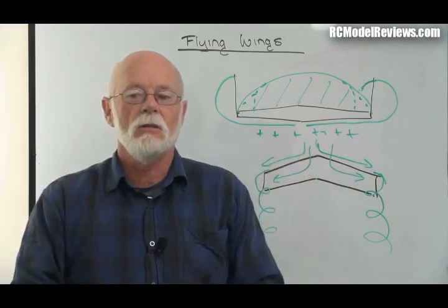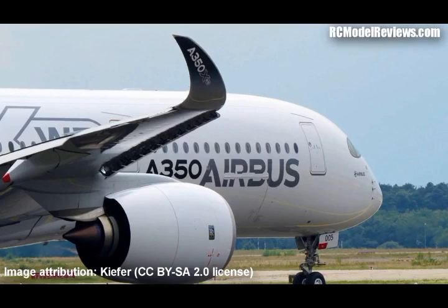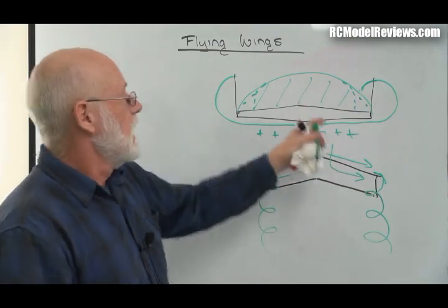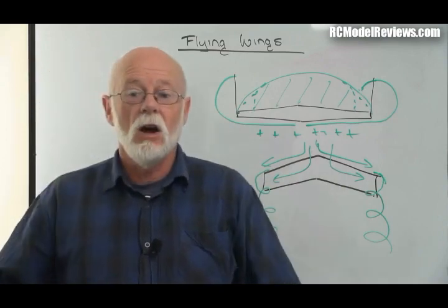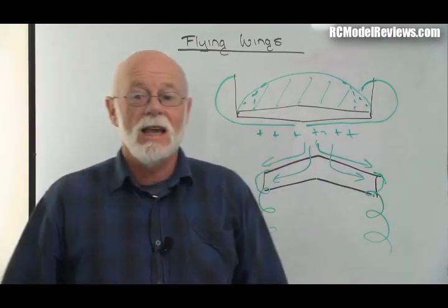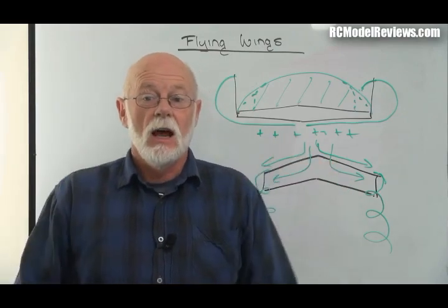And that's why you'll see a lot of airliners have tip fins now. In fact, virtually all of the high performance airliners have winglets on the end to stop this vortex, which reduces drag and also effectively makes it look like it's got a longer wing because it's not losing that final bit to the vortex as such. Brilliant. Tip fins are a good idea.